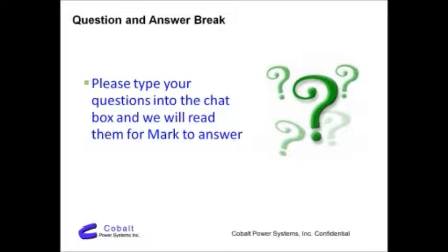Okay, a question from Joe here. What is the power loss due to the distance from the panels to the inverter for systems mounted remotely? Also, is it better to put the inverter close to the panels or close to the meter? Okay, great question about power loss through the wiring. Every system we install is custom designed. We design it for the specific case: for the homeowner, for the business, for the roof, for the ground, for the electric bill, and for the budget. And we always design for less than 1% total wiring loss. That means we pick whatever appropriate size of copper gives us that 1% or less wiring loss.